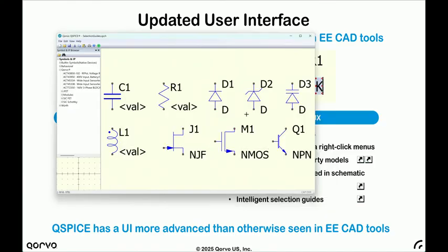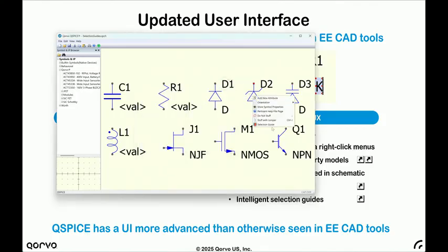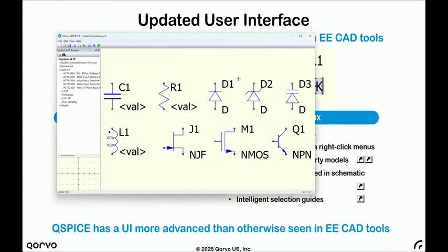For a varactor diode, you can sort them by grading coefficient, which is the parameter that says how fast the capacitance changes with reverse voltage. Or you can sort them by the Q. Zeners, you can sort them by the Zener impedance, not just the voltage. And so on. Oh, and for standard parts, you have a standard value, and you can have the 1%, 10%, all the different values will be shown. There are drop lists of all the standard values, whether it's E96 or 24 or 12. So the selection guides are all pretty good. Same with inductors.